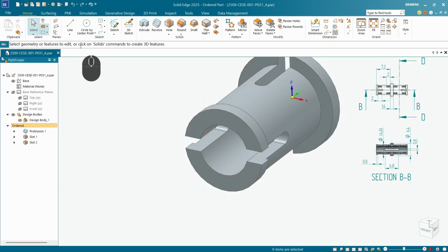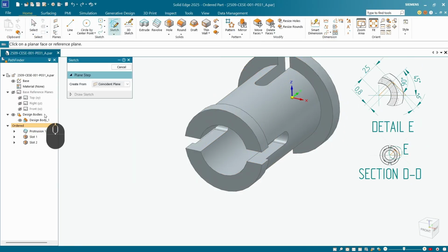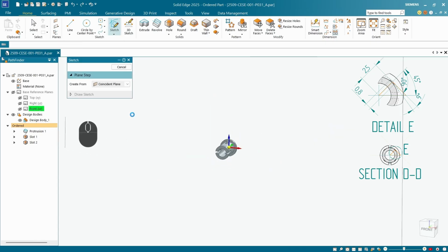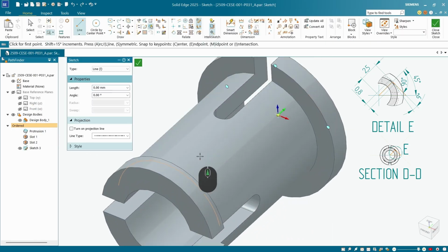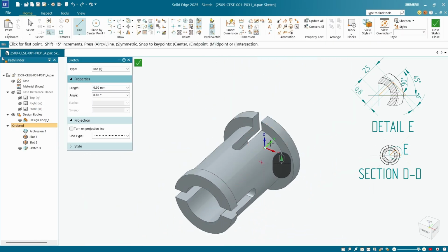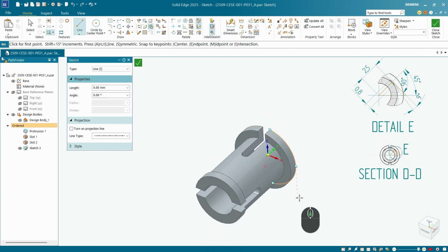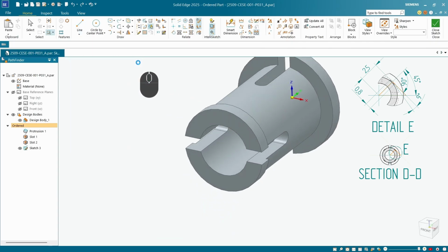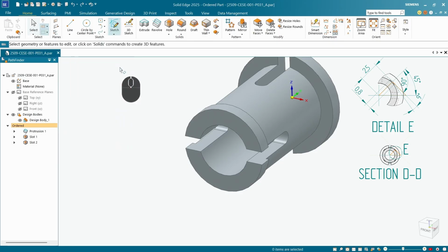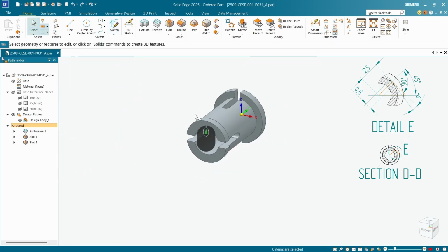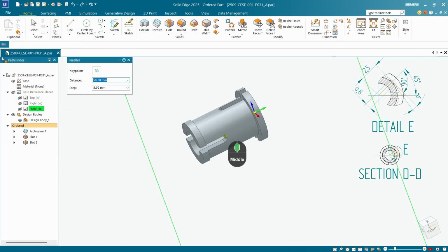So I'm going to choose Sketch, and I'm going to choose the front plane. And I suppose we're kind of getting a little bit in our own way. It's not a big deal, but part of this ridge is kind of overlapping part of our sketch, and I'd rather not have that. So I'm just going to temporarily close that sketch, click Cancel. Okay, and I'm going to create a parallel plane from our front plane, and we should be seeing a preview.